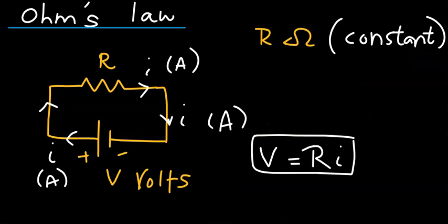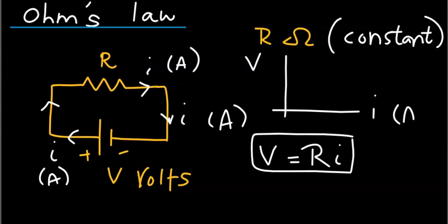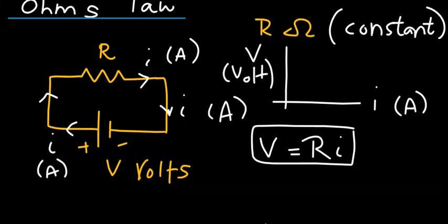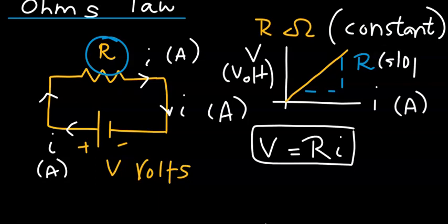Graphically, we can represent Ohm's law in the following manner. Suppose we have a graph. V is the voltage, and the horizontal axis is the current I, with a unit of ampere. So V is measured in the unit of volts. The dependence of I on V can be sketched in the following manner. It is quite simply a straight line, and the slope of this straight line is quite simply the constant resistance of that resistor, capital R. So R here is the slope of this VI graph.